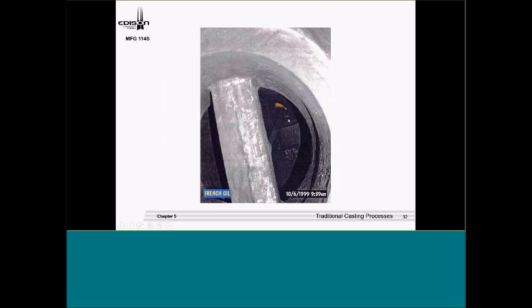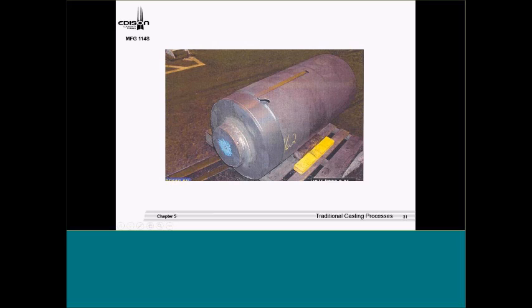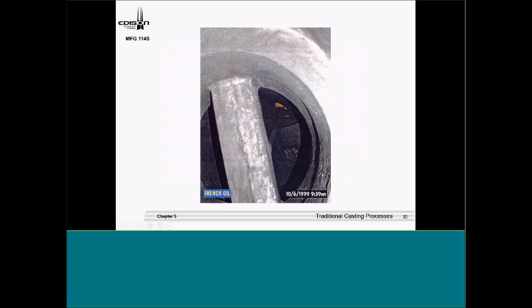There you can see that. We have this basin here, and we actually put in a center drill so we can have support and use our tailstock. They check up on this area here. So you have your tailstock coming in here, and you check up here, and end up doing your machining. But you can see now going through here how we talk about a core shift. If you look at the wall thickness from here to here versus the other side, it's quite a bit of difference there.